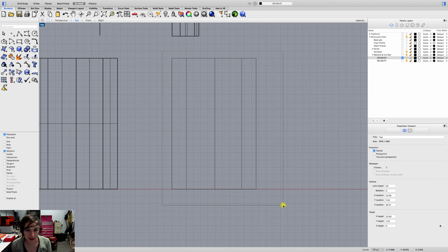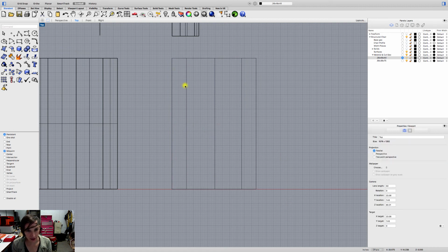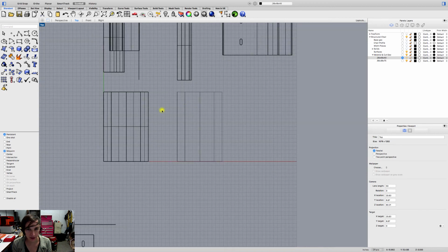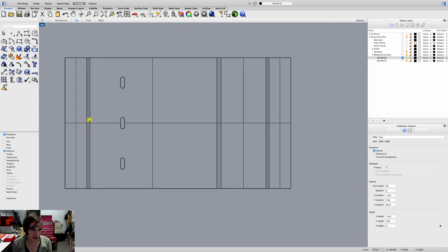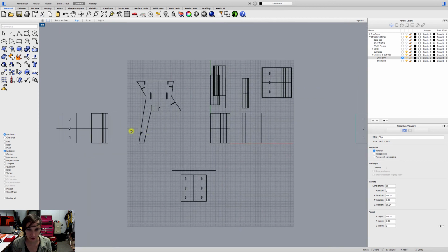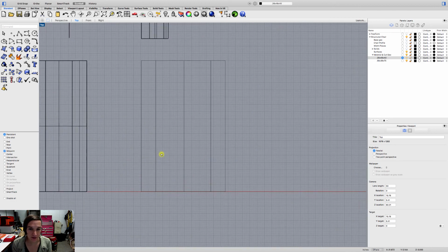Here's another quick method. Instead of doing curve boolean, I can explode everything. This method is only for bends that are sharp, unlike this one that has a more curved bend, and that geometry is reflected in this little rectangle. This has a sharp bend, which doesn't really have a geometry because it's just an edge.